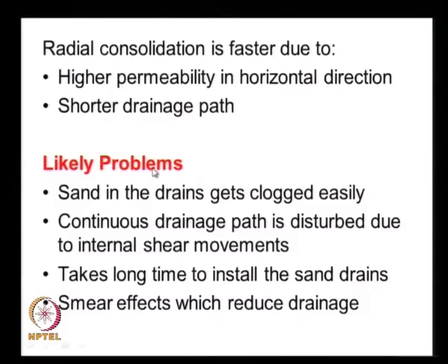And for a very long time the sand drains have been very popular for treating the soft clay soils, but then there were many instances where the sand drain treatment did not help in accelerating the pre-consolidation settlements, and some of the problems that were encountered are as follows.